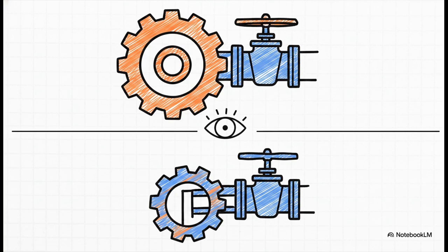Now this is where things get really cool. We're going to break down the 3 distinct mathematical lenses of the PID algorithm, and we begin with the P, the proportional term. I want you to think of this as the present. This first tool is super straightforward. It drives the output based strictly on the current size of the error. If the error is massive, it makes a massive correction. If the error is tiny, the correction is tiny. It literally just multiplies the error by a tuning gain. It's reacting purely to exactly what is happening right now.